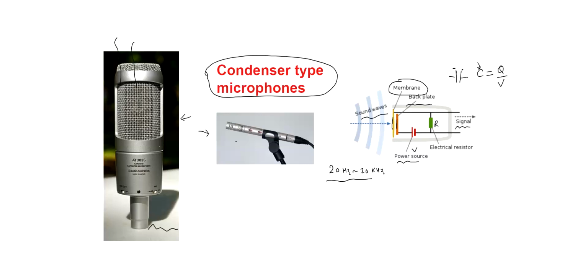And the charge on the capacitor is maintained at a fixed value by this DC potential, so the voltage across the two plates of this capacitance is essentially changing instantaneously with respect to capacitance. So when there is air pressure that changes the capacitance, the voltage is going to change, and that voltage is measured, which is an instantaneous voltage proportional to the change in capacitance.